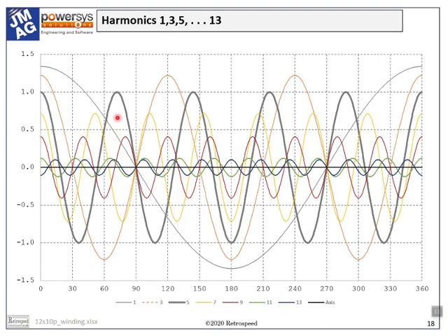The idea that a machine could be operating with harmonic MMF components significantly larger than its working harmonic is quite a shock. The idea that a machine should synchronize with a harmonic much lower than some of its larger harmonics is quite a shock. The lowest order harmonic is in fact the two-pole harmonic, P equals 1, which is the first mechanical harmonic.